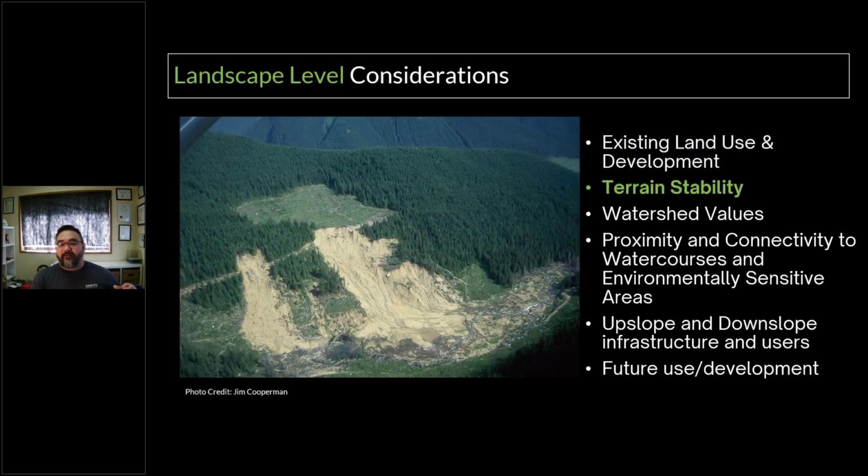In the same way, terrain stability is going to play a huge role, and we could do a whole series on just the different types of impacts that you can have, but you need to understand where you put the road and the development that you're accessing, how that's going to impact terrain stability. And sometimes it's not super obvious. This is an example of an area with flat over steep, and